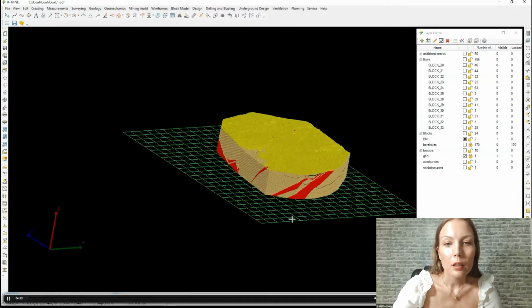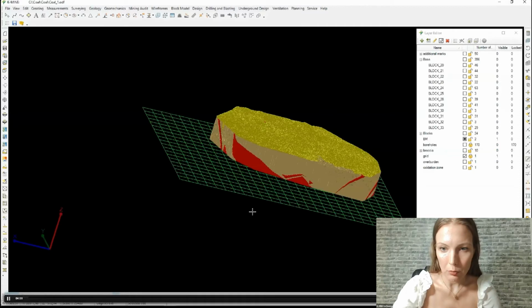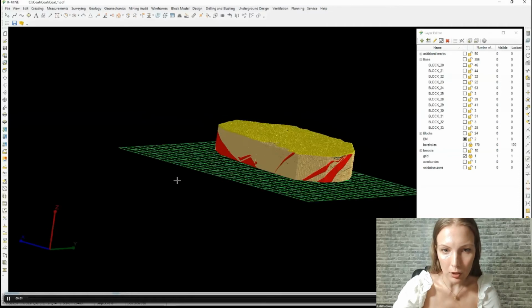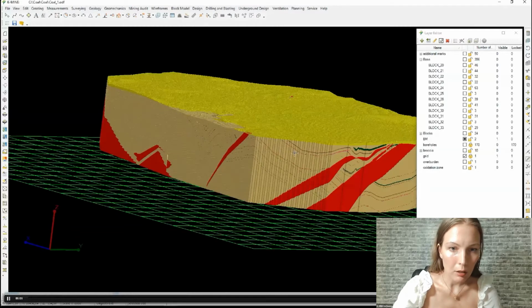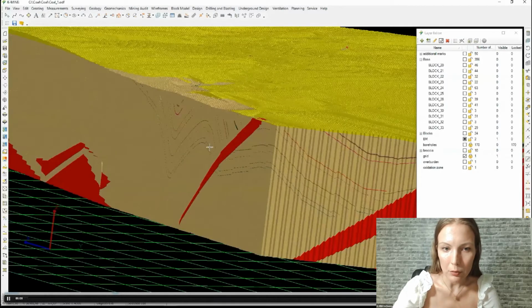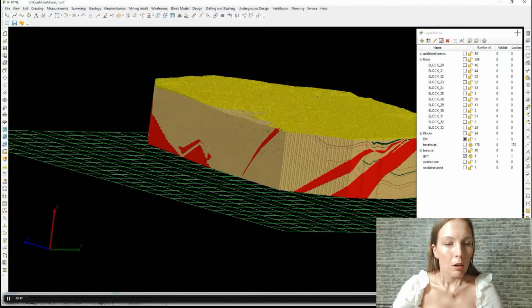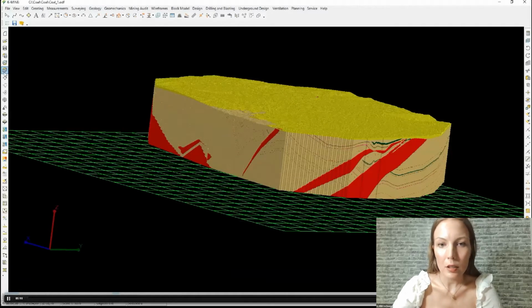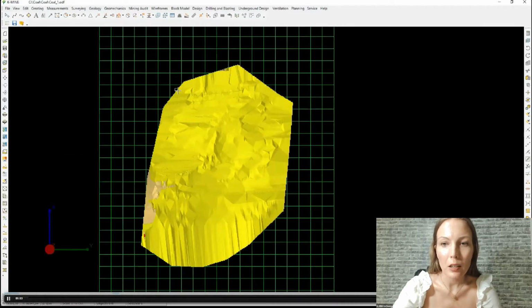If you simulate the deposit with tectonic dislocations, the marker surface should be created separately for each tectonic block. And before creating a block model with a complex tectonic structure, you need to create boundaries for each tectonic block. Also, interpolation data analysis of elevation marks in marker seam should be performed within the wireframe of each tectonic block.